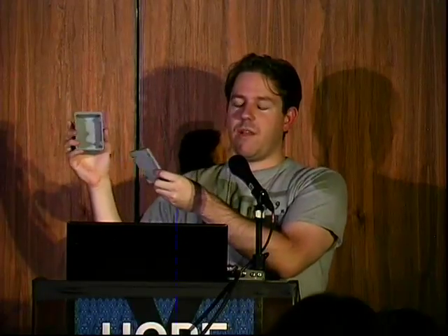And then controlling the way it implements different features, there's a lot more options and a lot more complexity in doing the machining side of it than there is in doing the 3D printing, just in terms of how the G-code works. If you were to open up a machining file for something like this versus a 3D printing file for something like this, there's going to be a lot more in the machining file that is setup and configuration and information to the machine on what it's doing and how it's doing it, not just movements. The 3D printing world is very, very just movement driven, and it just feeds plastic or PLA at a constant rate.